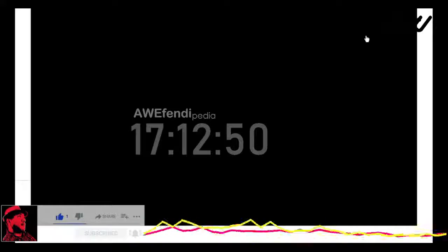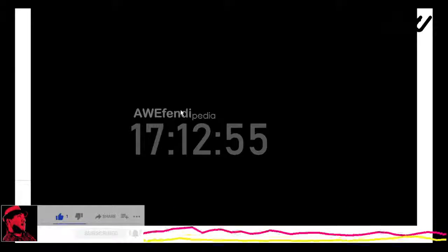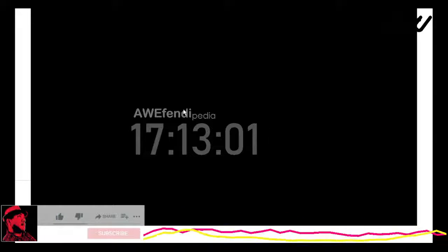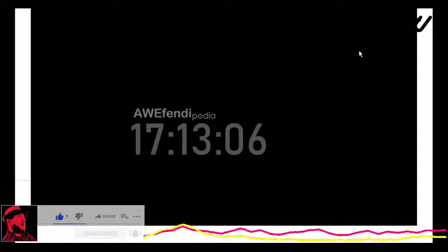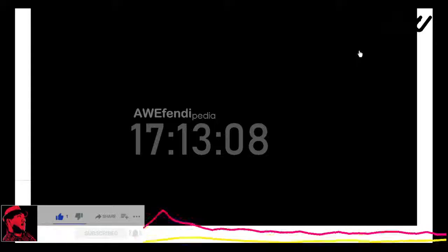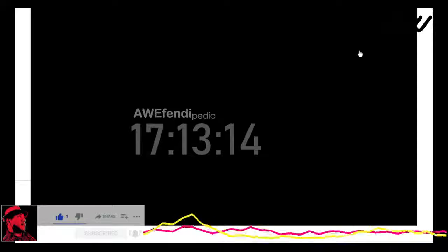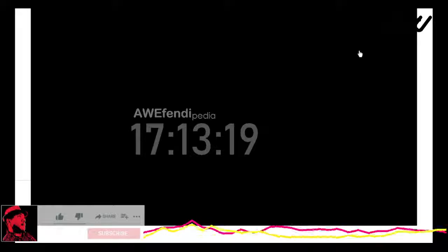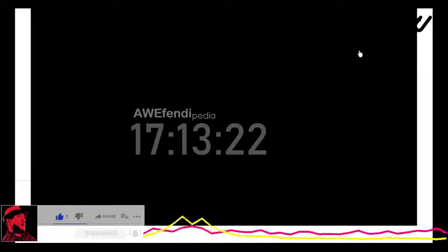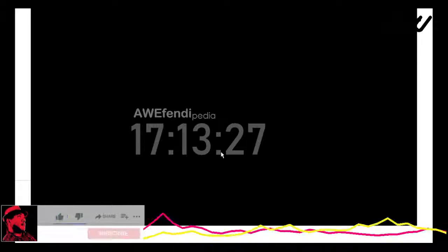Why is creating geometry a little more complicated than just a horizontal and a vertical down the center of the roadway? So here's a representation of the model that we're going to construct going forward. As we think about what we need to develop geometrically for this alignment, you can see the tapers horizontally as we move from the existing roadway corridor into our widened section. Our goal is to widen the pavement to the interior.